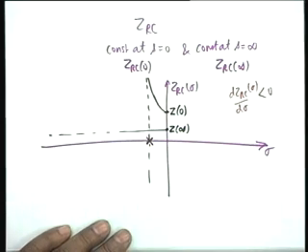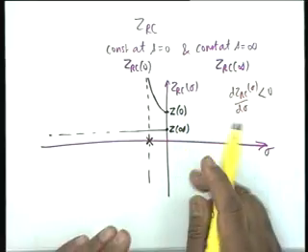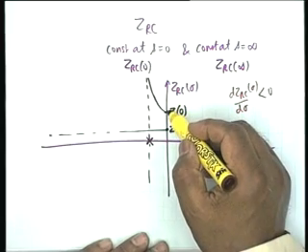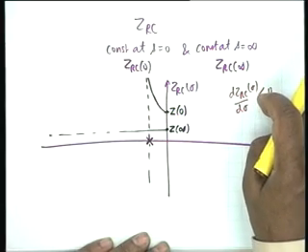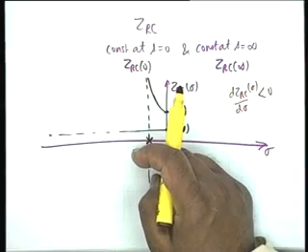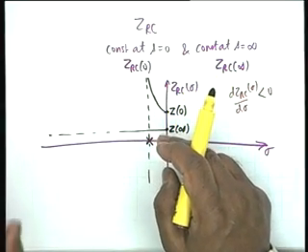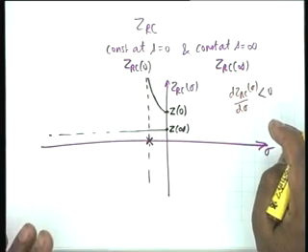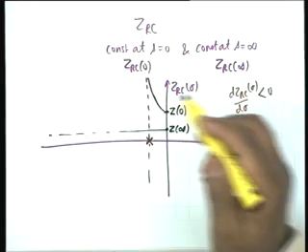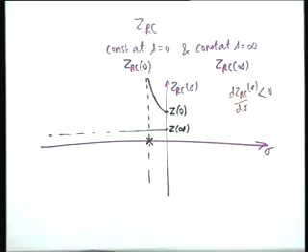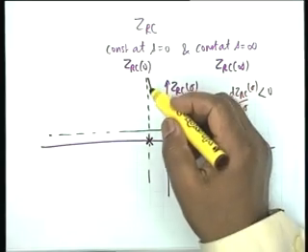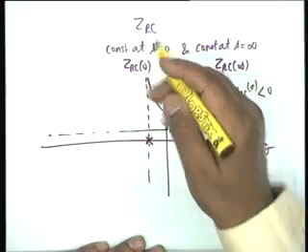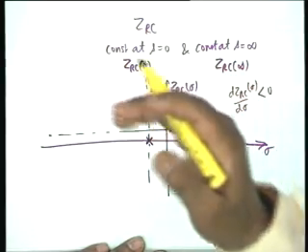Is that clear? You see, I am plotting Z_RC of sigma on the negative real axis. The function has to go up because the slope is negative. It cannot come down. If it could come down, then we could have the possibility of a 0. The slope has to be strictly negative, which means that it cannot have a maximum or minimum. Isn't that right? And therefore it has to go monotonically. How far can it go? It can go to infinity. All right, let it go to infinity.